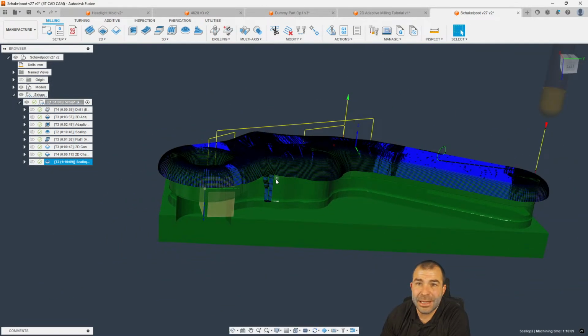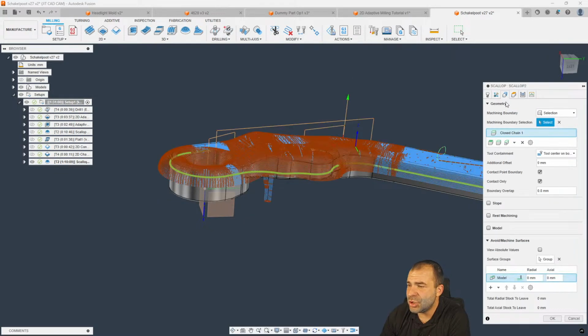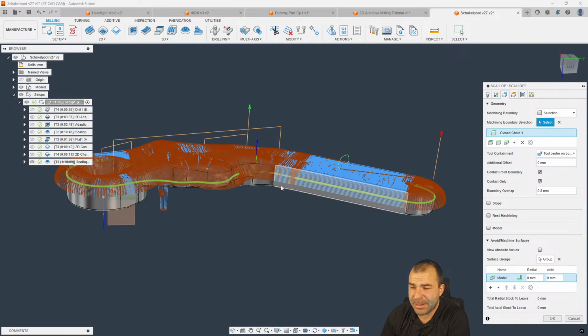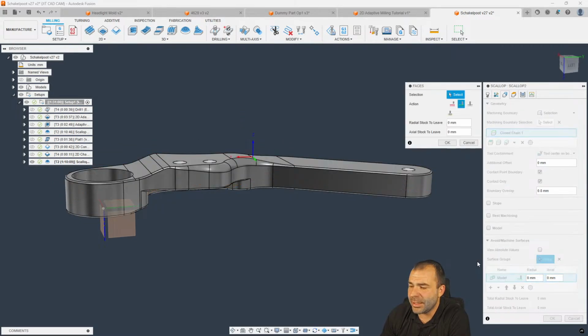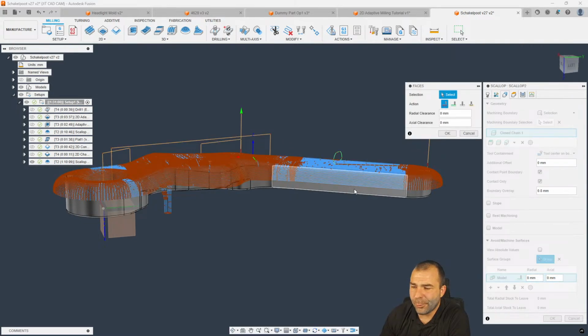So this is where I tell people that you want to go through each one of these steps and do the absolute most that you can here before going on to the next step. Now this is where I could add in avoid touch machining if I would want, right? I've gotten this path pretty straightforward, narrowed down to where I want it. This is where we could go in and now add our avoid surfaces, right?